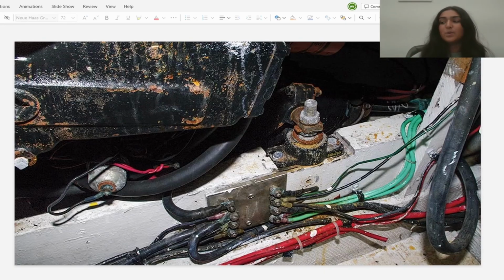An example of this is when moisture gets into the electrical components of the ship, the copper wire will begin to oxidize, generating a greenish tint, which creates resistance. This means that the resistance is generating heat in direct relation to the amount of current flowing through the metal that's been oxidized. The biggest drawback of this process is that it stays inactive, so until the electricity has been turned on, no one will be able to tell that this oxidation occurred. However, once the electricity has been turned on, it can quickly turn into a fire hazard,